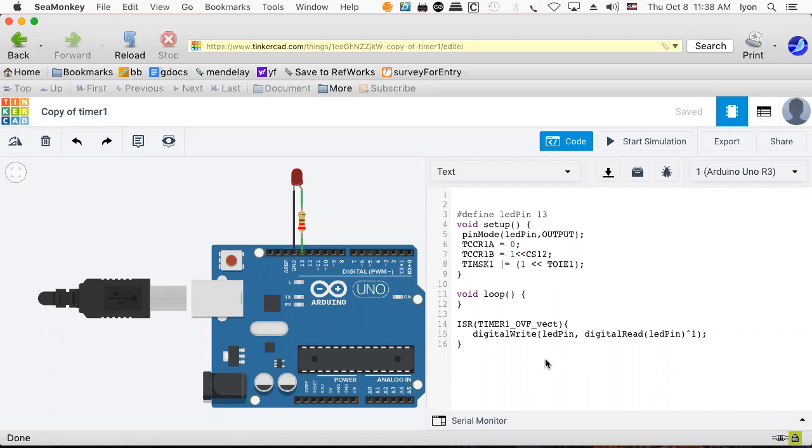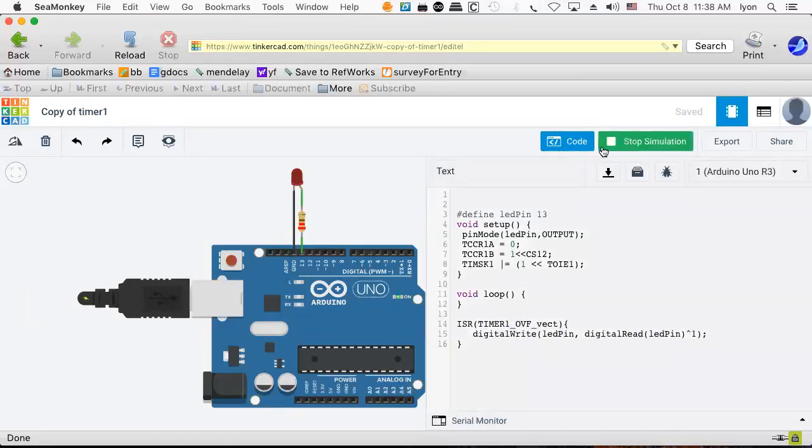And now we can make an interrupt service routine out of blinking the LED. And so then, this is what it did anyway when we did a delay. Only now we can do whatever we want to in the loop, even nothing at all. And this will wake up every second, and it will read what's in the present digital pin, use exclusive OR to invert it, and then write it back out. So in principle, this should blink, I hope, and it does. Look, light goes on, light goes off, goes on, light goes off.